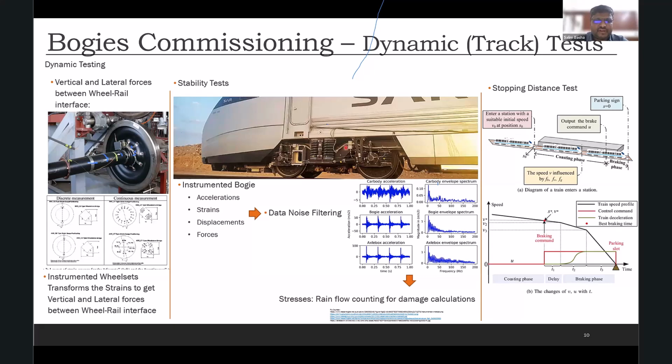Now another aspect is the stability of the train. So we put accelerometers all across the train or at key locations, which will continuously monitor the vibration characteristics of the train. My car body is expected not to vibrate too much, not to oscillate too much. So we find the right sweet spot and put an accelerometer there. Similarly, on the axle box, we put some accelerometers.